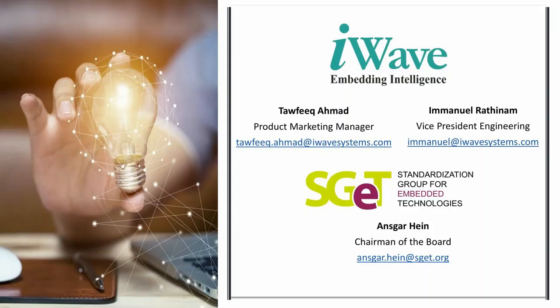The first question I see is from Alberto. For similar specs of the processor, memories, etc., does the OSM standard imply an increment of the cost compared to the SMARC standard? No, actually it is less because of the PCB cost and no connector cost. The assembly cost is always subject to which EMS or contract manufacturer you use. But based on our experience, as Taufik showed, we have an OSM module on the 8M Plus and we also have one with SMARC, and we definitely see a $3 or $4 lower price.